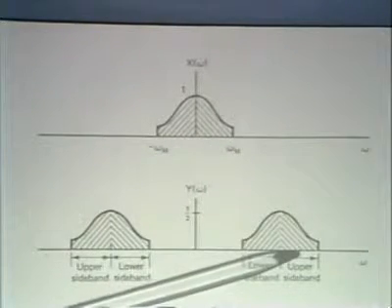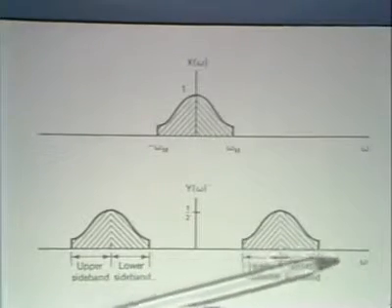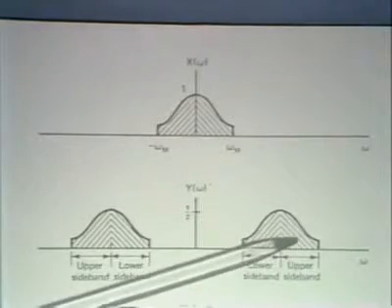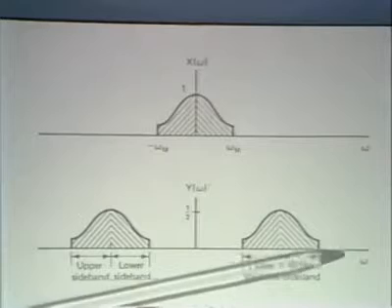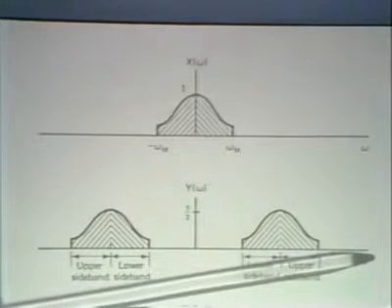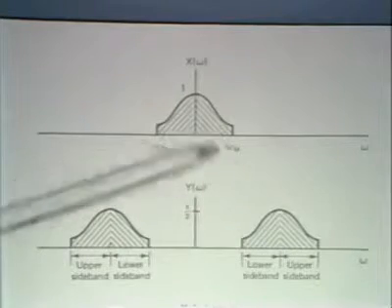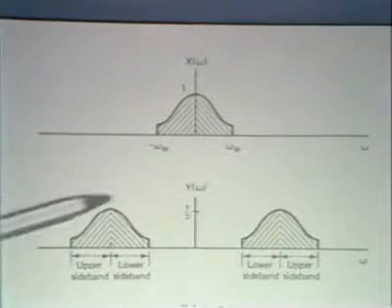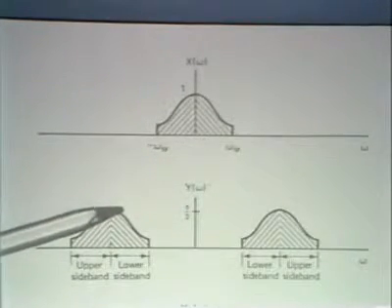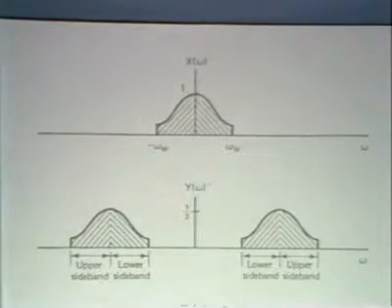By the time we've shifted it, thinking of positive and negative frequencies, we've used up twice as much of the frequency spectrum. Well, you could say, okay, let's just shift this up this way and get rid of this part. That's, of course, what the complex exponential carrier did.